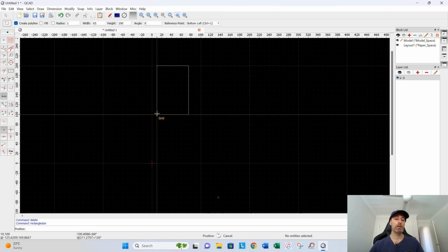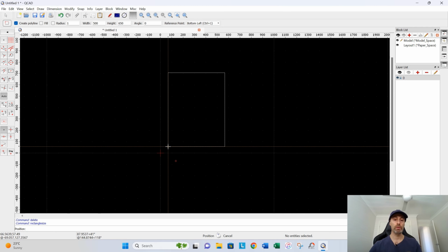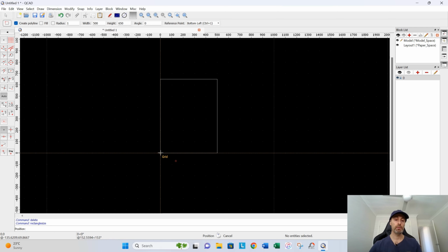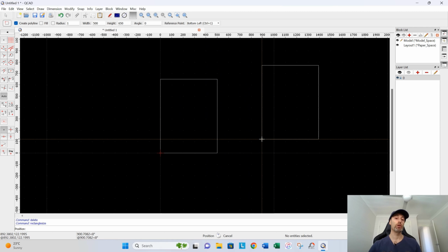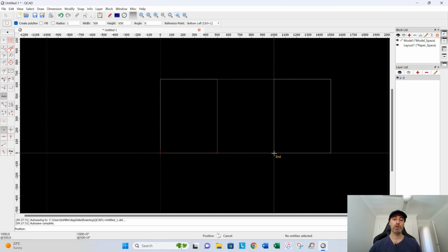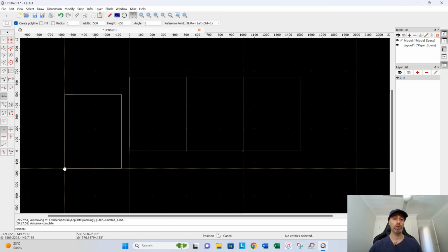So I'm going to be drawing 3 doors first. I want these doors at a width of 500 by around 650 high. So if I zoom out, that's my door, for example. I'm going to left click there, and I've still got that square, which is very handy if I want to do multiple doors, for example, or the same run. I'm going to start the next one there, left click, another one, left click. So already I've got 3 doors representing cabinets there.